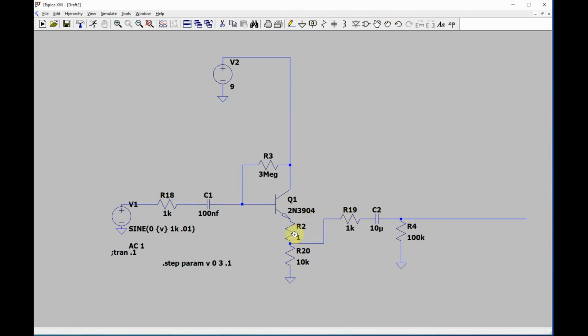Now as you move this up and down, you're actually moving the bias up and down also, and that'll equilibrate across here. But if you move it up and down really fast back and forth, like on a slider on a mixing board or something, you'll get some transient DC offset, which can sound like a big oomp or whoomp. So it's not for really fast moving controls. But it's usually not a problem most of the time.